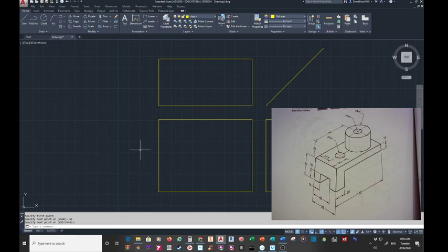If I had the side view on this side, I would have the miter line over here, which is what I did in the first example for my inch video. I did a left side view because that's what you need to do. It doesn't matter which side you do, as long as you do a left or a right. Some of the ones you're going to do may have left side views, some may have right side views. Everybody wants to burn the right side view into your retina, but it doesn't have to be.